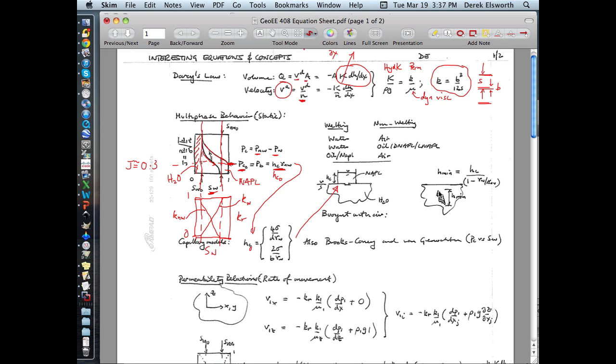And once you get this little ganglion present within the subsurface, then the height that you have to have for it to keep going and to never stop is given by this. This is HC0, I guess. And these are just the unit weights of the two different materials. So if you know what the bubbling entry pressure is, then you'd know what this is by just this relationship here.